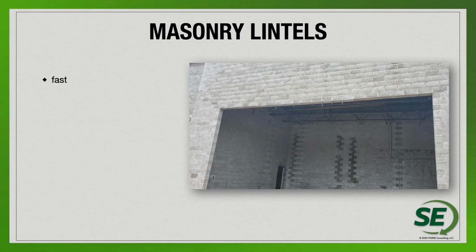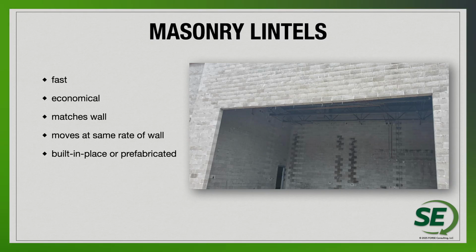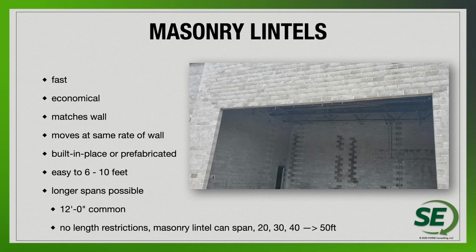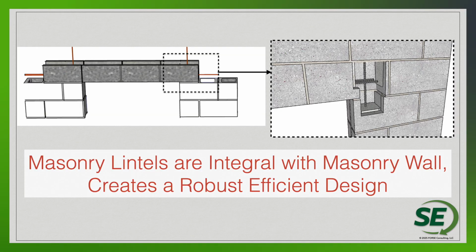So masonry lintels, we like to talk about those for a lot of good reasons. It really doesn't require any more demands on shoring. You have to educate the contractors in terms of what's available in terms of prefabrication, or looking at different types of shoring systems that are much more readily available. We don't need to leave the shoring in the wall, is what I like to say for the steel lintel options. We can just put in some very simple shoring elements, and then remove it and build with masonry for these masonry lintels. So masonry lintels are going to be very integral, very robust, and they're going to have a lot more capacity.